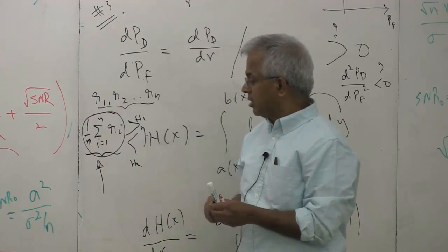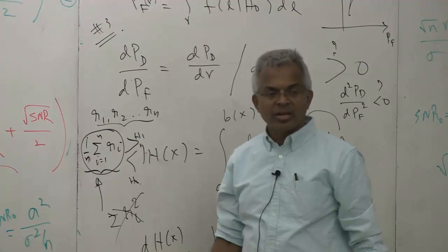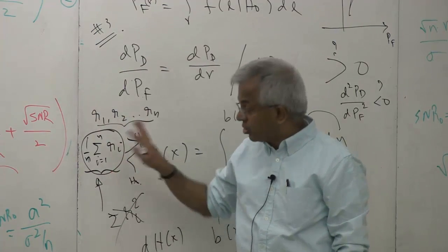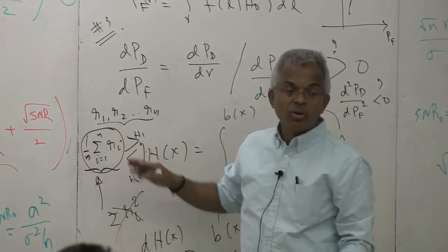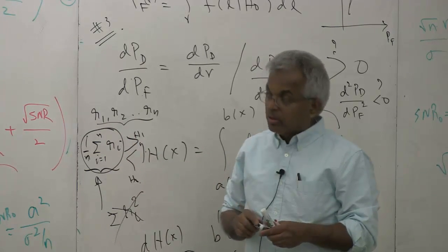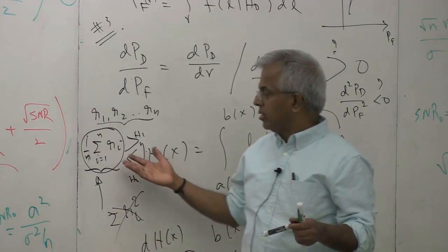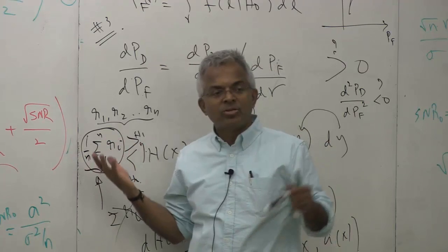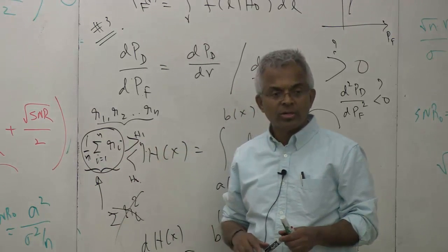Of course, you can say, why don't I square the data and so on. In this problem, this is not the right thing to do. The right thing to do is this, because we proved it optimally. So this is the receiver you are looking for. Remember, you are looking for some optimal processing. In this problem, the optimal processing is very simple. You just take the average of the data and compare it with the threshold.